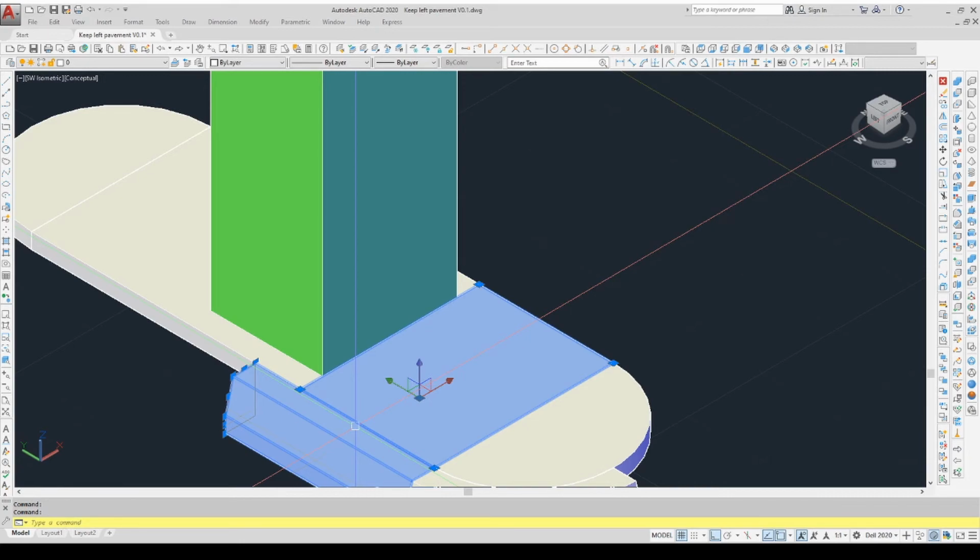And that means that we have to get clever in 2D, 3D CAD and put in a trough. How on earth do you do that? Well, I've discovered, I did try putting triangles in, but like the chamfer command, there's also another command which is like chamfer, which is in 2D fillet, and in 3D it's still fillet, but essentially what it's capable of doing is selecting a right angle edge and putting a little round curve on it.